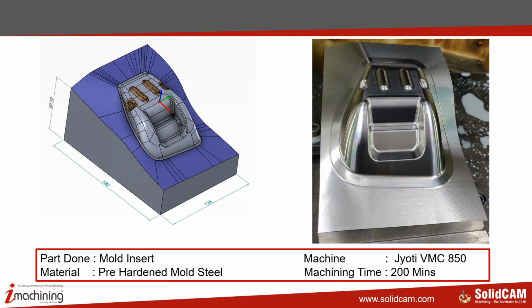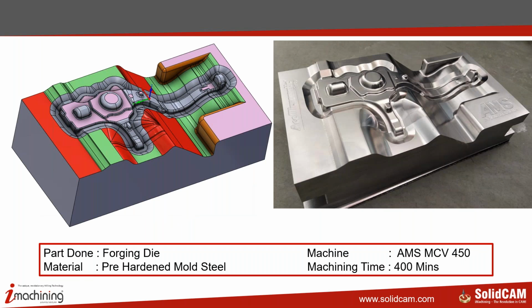The small insert that I showed you, 180 by 135 by 88, was also done on a Jyoti VMC 850, cut in 200 minutes, and this is as seen on the machine. You can still see the coolant lying around, no hand touching of this part, the kind of surface quality that you generate. The last part is the one that you just saw. Again, this is as coming out from the machine. This was done on an AMS MCV 450 in 400 minutes on a pre-hardened mold steel, 48 HRC. You can see that the surface quality that comes out from this is excellent. No hand touching is required if you have done the machining in the right way.